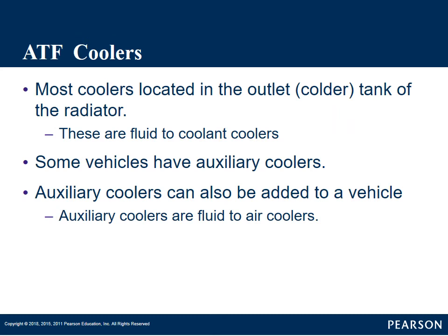Again, we talked about most coolers being located in the outlet tank of the radiator. Some vehicles have auxiliary coolers on them. They may be standalone, to where that's all they have. They don't run it through the radiator. Those are ones that you see with the special valve on them that doesn't allow it to circulate through that cooler until the temperature of the transmission gets up to a certain amount. Once it gets up to a certain amount, that valve moves and then it'll circulate through the cooler.